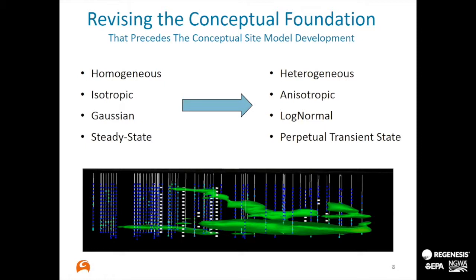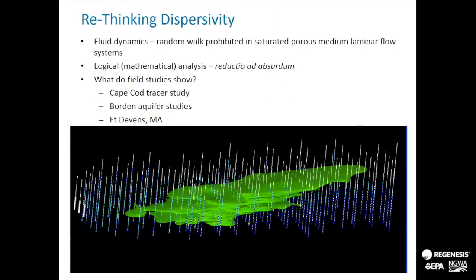One of the things we focused a lot on in remediation hydraulics, and probably over-focused to some extent, is the dispersivity argument. It still haunts us. There's a lot of our simplified models that are founded on the advection-dispersion equation. There are mathematical flaws to that, and observation tells us that transverse dispersivity is always extremely low wherever it's been carefully measured, but it persists.